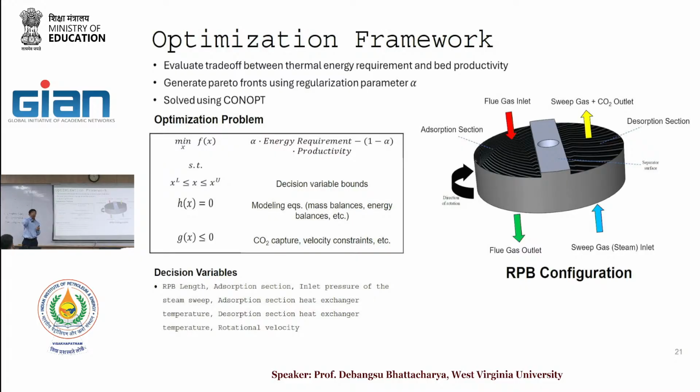And the steam flow rate and all of this is integrated over time. How much steam you need for the desorption, through the entire desorption cycle, you integrate that. That's the total amount of steam that you need. So those are all time-integrated values, and then the capital costs are done separately, and that is how it is done. Yes, so I will say that those papers which have the economic analysis try to explain how this type of thing should be costed.